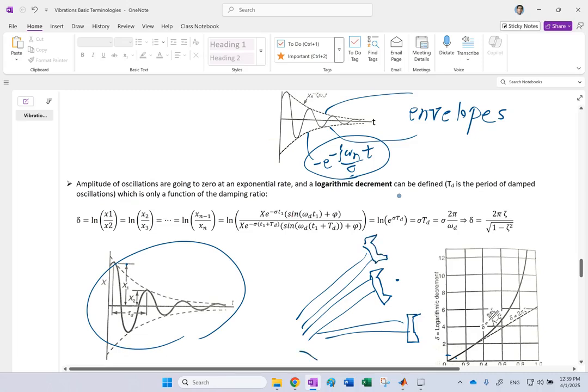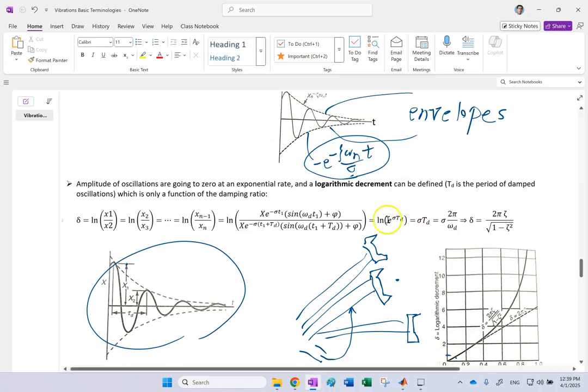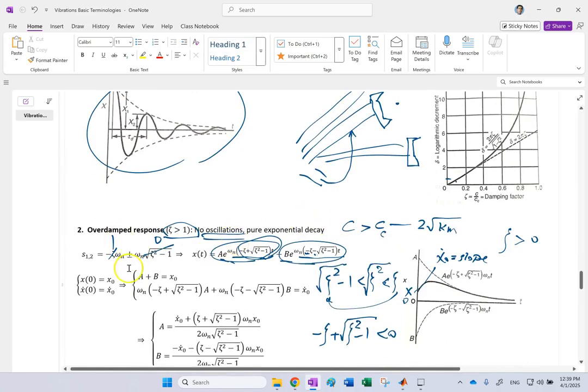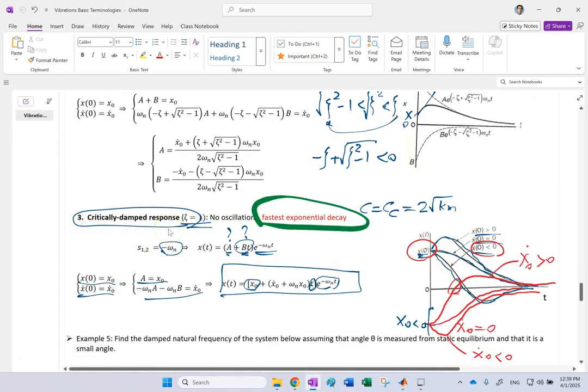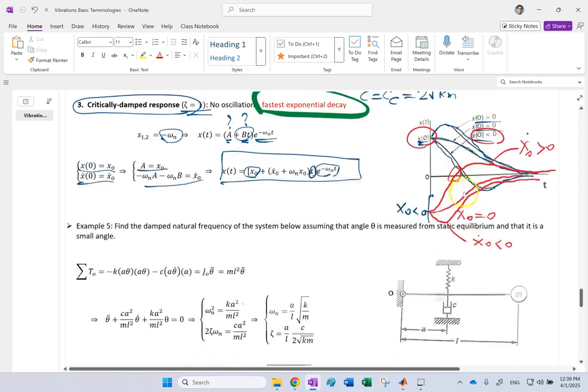You want it to start from the initial position, go directly there and stop. No overshoot, no undershoot. You really want a critically damped or overdamped response, and because critically damped goes to 0 a little bit faster, we typically pick a critically damped response in most PD tuning or PID tuning for robot controls. So just keep that in mind.